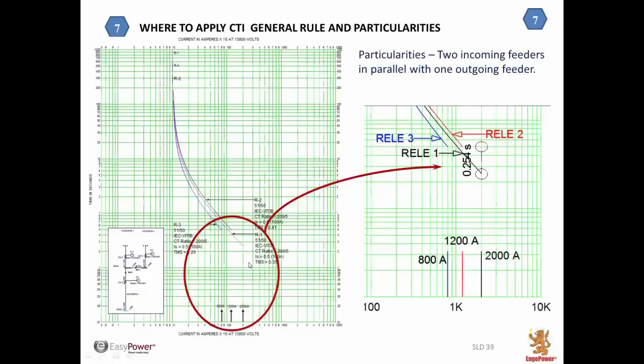Now we are going to have the surprise. The surprise is that if we go into the TCC, we see that the curve of the relay 3 is below the relay 2 on the TCC, and the relay 2 is just a little bit above the relay 1. Watching this curve, those who are not normally used to doing TCC are going to see that the system is not coordinated. And I can guarantee to you that they are.